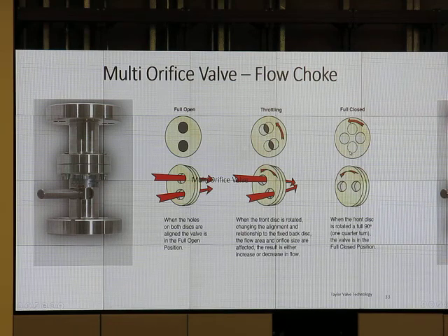You don't ever want to use a choke for a shutoff on any kind of application. Don't depend on it for a shutoff. The choke is what will take the erosional wear. And so if you're on a wellhead, you want to make sure you close a valve that gives you control of the well. The choke can be closed, but don't count on it.